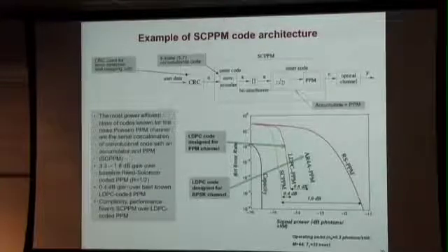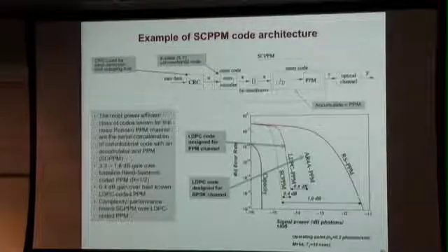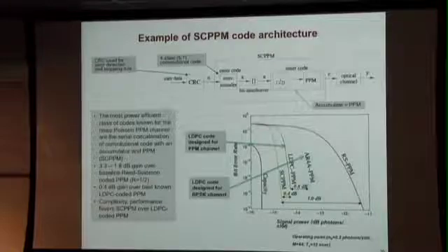We have a convolutional encoder as an outer code, a bit interleaver, and what's called an accumulator. I'm not going to get into the details here, but basically in the LDPC world, this is used a lot as part of an LDPC code. But in this particular application, Bruce has concatenated it with the PPM modulation, which is what's important for making the duty cycle low overall.